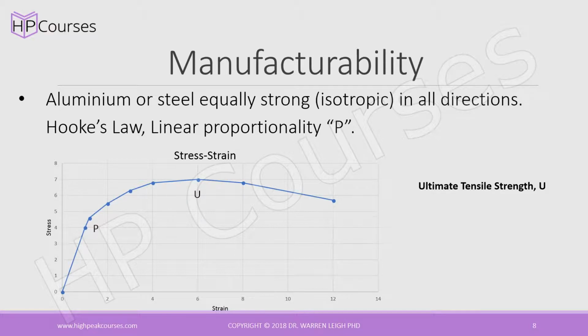Slide 8. Note that the stress-strain diagram for isotropic materials generally is initially straight up to point P, which is its limit of proportionality. This is referenced to the applied load and the material strain. After point P, the isotropic material can still take stress, but now its behaviour is following an eventual failure curve. In reality, we receive a warning that the metal is getting overloaded and will ultimately fail.